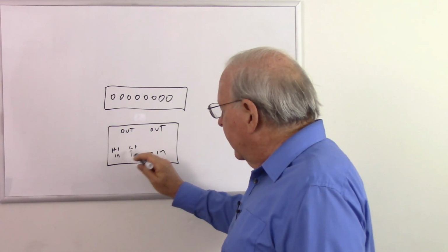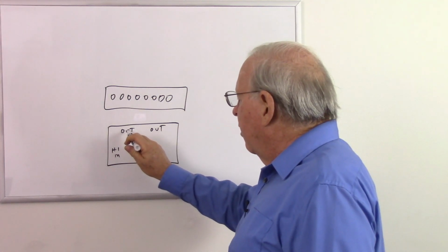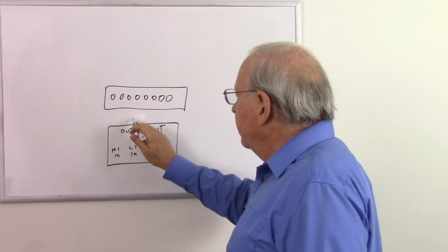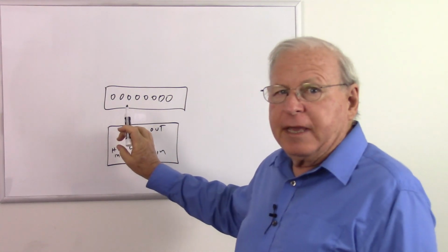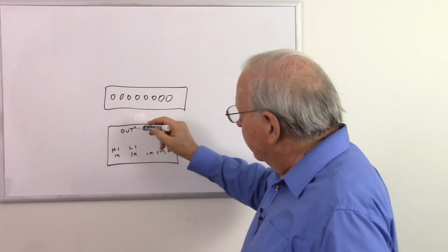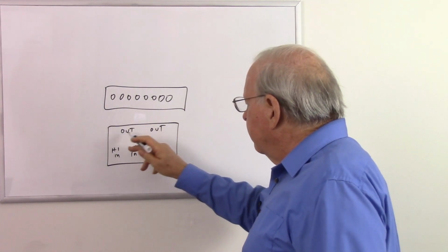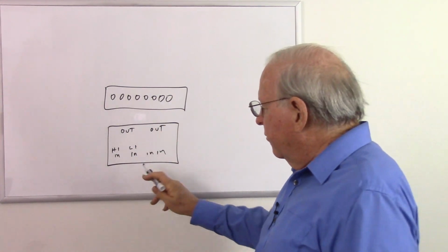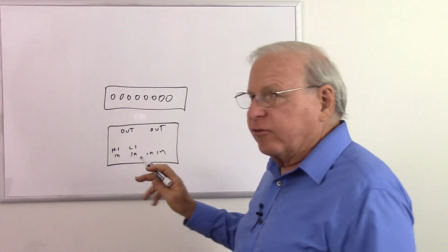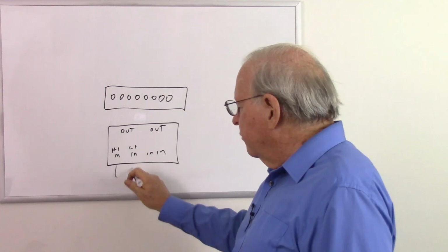But you might find out that you have inputs for both high and low impedance devices, and your outputs will be matched to the mixer. So they're probably going to be a low impedance output, but we're not going to worry about that because we know they're matched and that's going to work. So you have several inputs and one or more outputs, and so you can match your high or low impedance. So if you have high impedance microphones, low impedance microphones, and whatever.